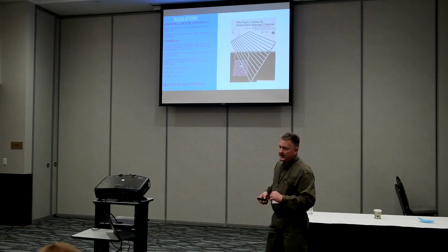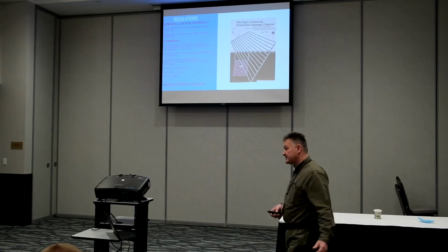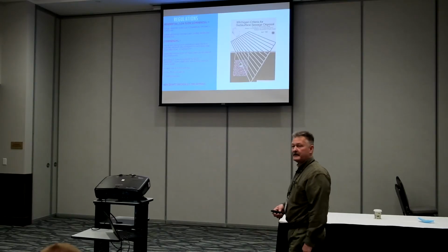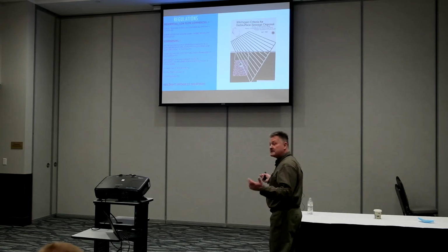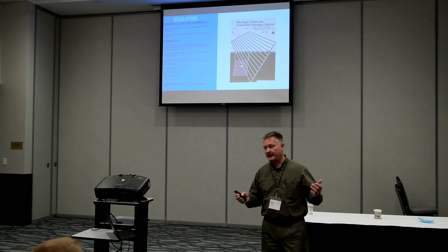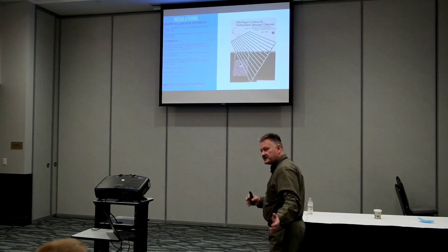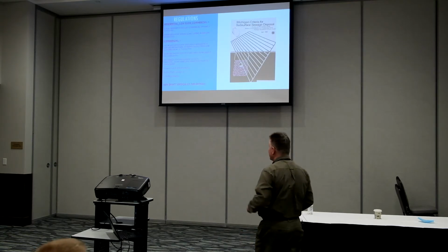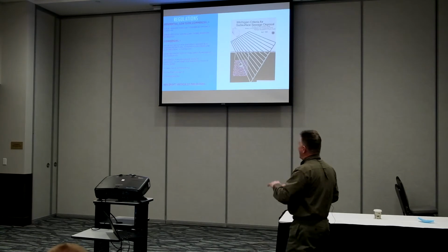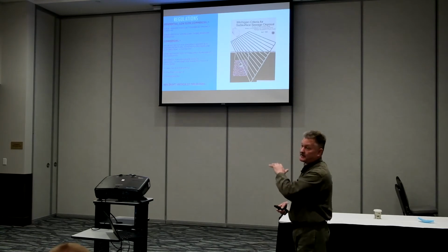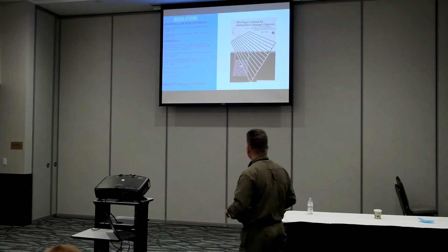It also indicates in there that you can have no more than 3 or 4 doses to that system a day. So if we have a large flow situation, we're sending a huge slug every dose out there, and how does that affect our treatment? It doesn't address the situation that, say, we have a restaurant that in a 6-hour period discharges 1,000 gallons all at once. Well, conventional pumping systems or gravity is just going to go right out to the field. So it doesn't address how we handle those big peak flows either. If you apply the new draft version of the criteria, that hits more on where we should be when we're looking at commercial designs.